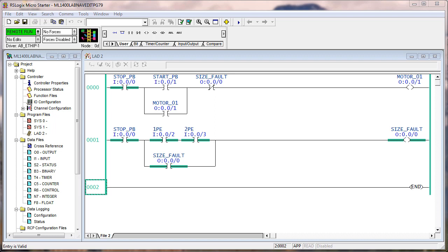Now, most conveyor systems of any repute sound an alarm or a horn when they're going to start back up. If the operator pulled off the carton, you could have it programmed so a horn sounds for several seconds and then the conveyor starts up. Typically, the operator has to pull off the rogue part or the jam, clear the jam, and then hit a button. Then that sounds the horn. You know how people walk across conveyors. So it sounds the horn for 2, 3, 4, 5 seconds, and then it starts up. So you're warning people that there's motion.